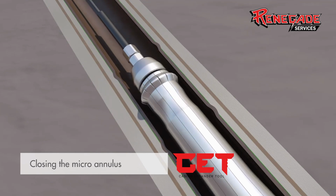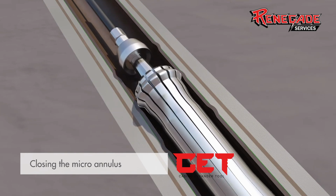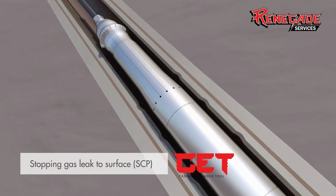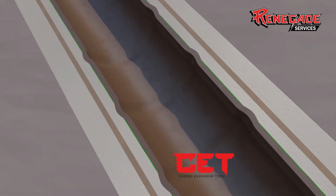Now when they run this tool, they do a series of 3 what we call crimps. They'll crimp it in the bottom of the area, the top, and then they'll come back and do it in the middle. Now that would help make sure that the cement doesn't actually move uphole or downhole as you're applying pressure on certain areas. So they do bottom, then top, and then the middle to make sure that that channel is sealed.